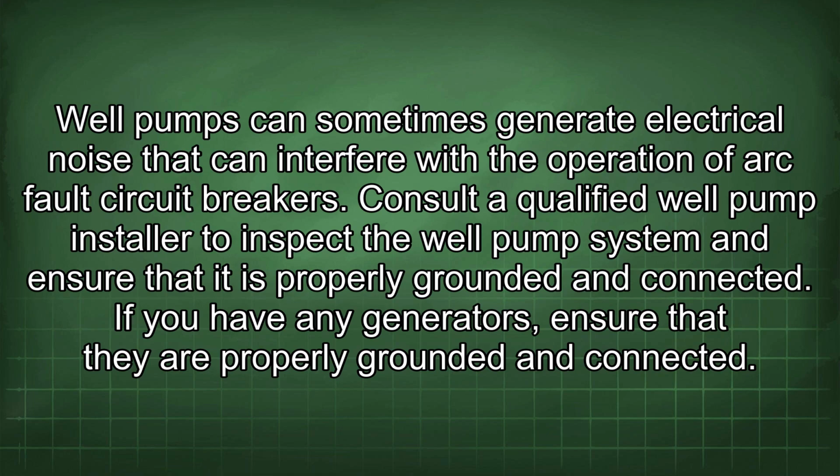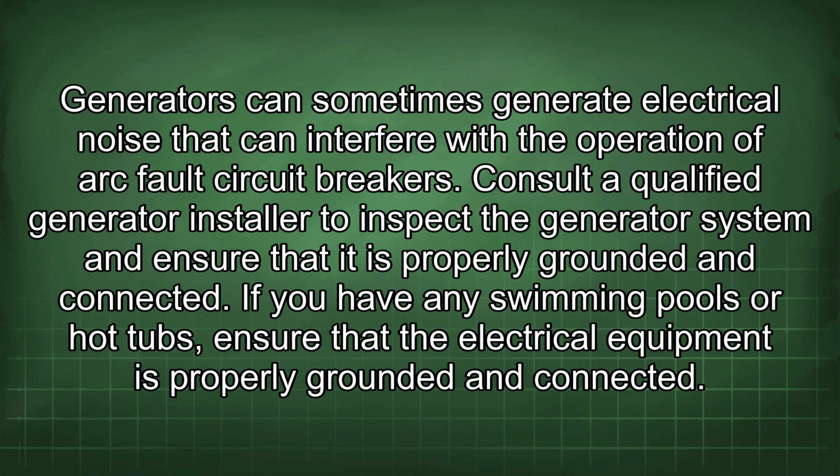If you have any generators, ensure that they are properly grounded and connected. Generators can sometimes generate electrical noise that can interfere with the operation of arc fault circuit breakers. Consult a qualified generator installer to inspect the generator system and ensure that it is properly grounded and connected.